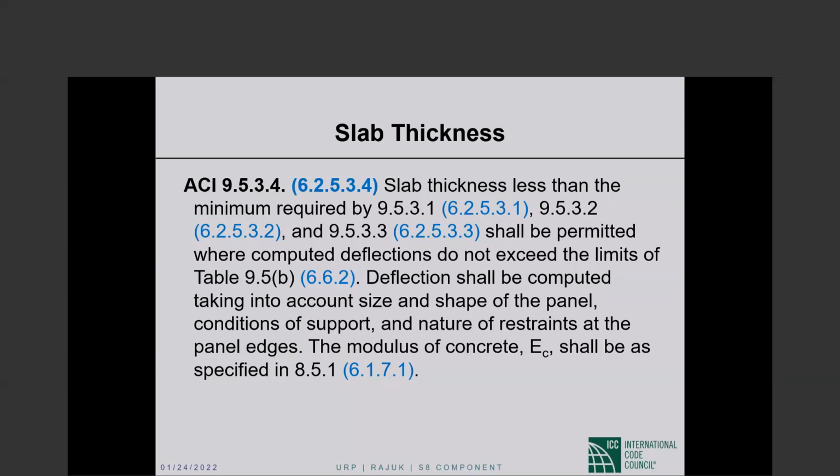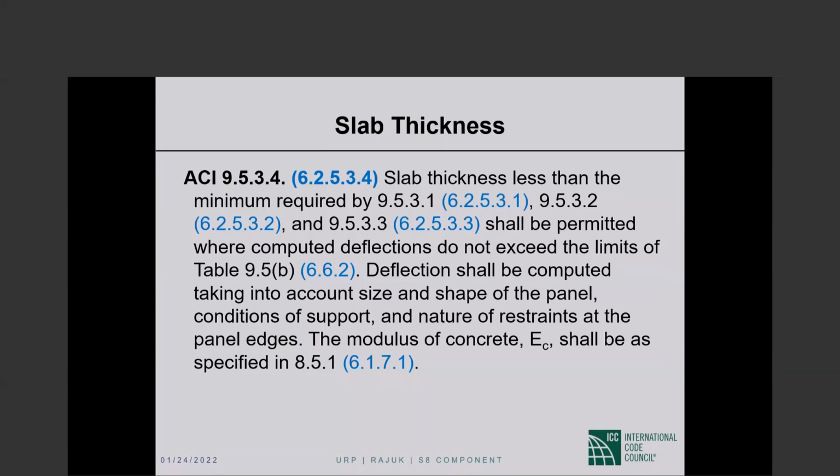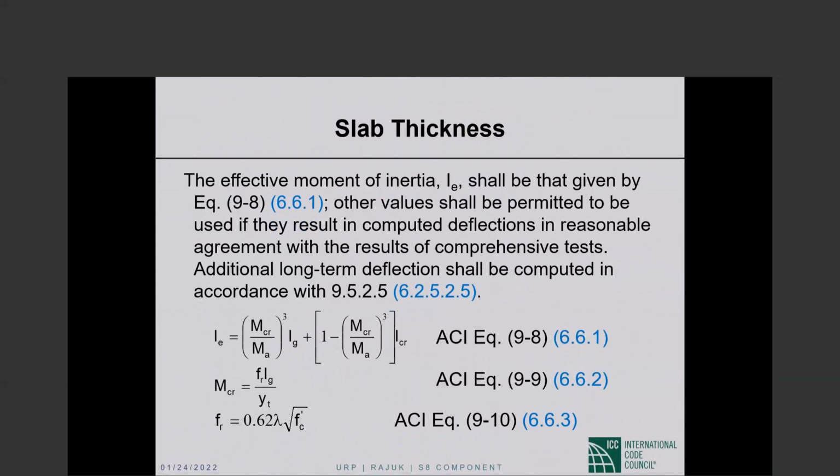But to calculate the deflection of a two-way slab is infinitely more complicated than calculating the deflection of a beam. I'm not going to say it cannot be done, but it is difficult to do. So this is not an option that you should normally choose.